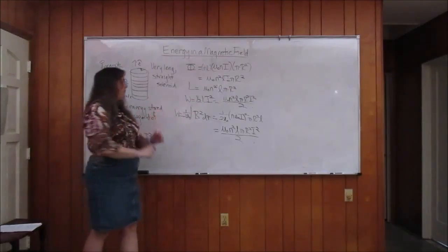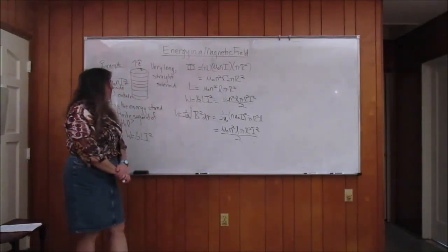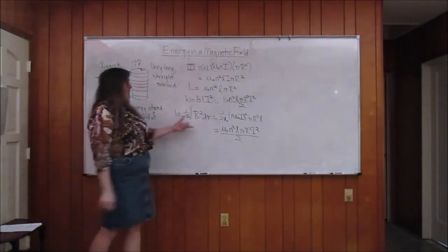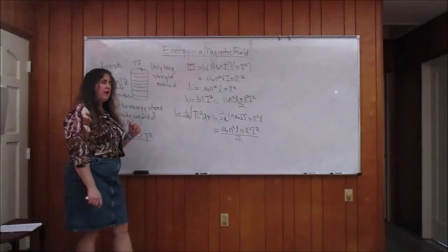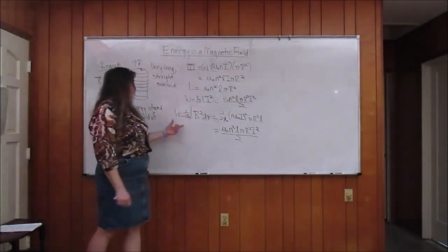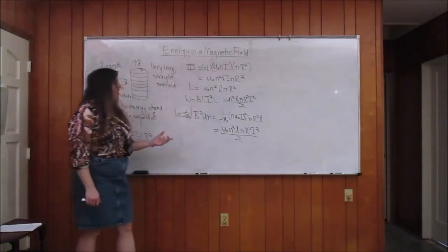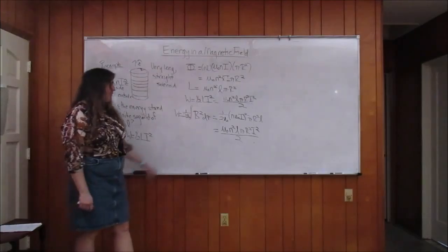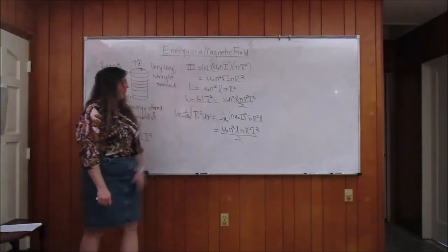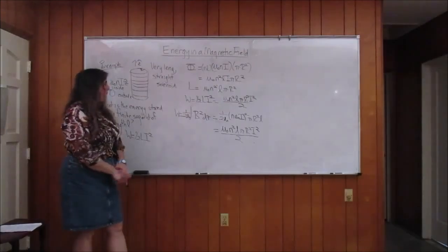So as many times in physics, there's more than one way to solve a problem. And this suggests a technique, actually, for calculating the self-inductance of a certain object. If you can figure out what the energy is stored in the magnetic fields, and then use this expression to determine what the self-inductance is by setting this equal to this, which is useful in certain circumstances. Okay?